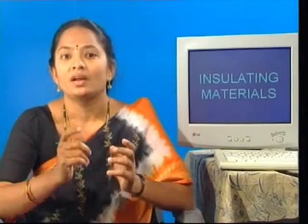The next factor is resistance to abrasion, tear, shear and impact. Take the case of an insulator used between the commutator segments, which are subjected to abrasive action, that is, the effect on the insulation caused by scraping during the running of the motor. The insulating material must be able to withstand these forces, hence it should be hard and mechanically strong.